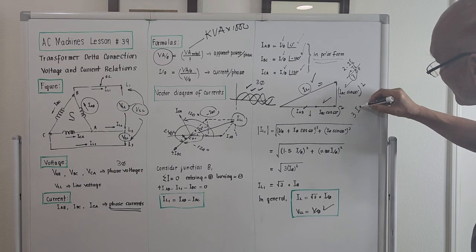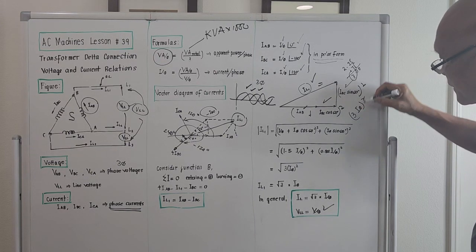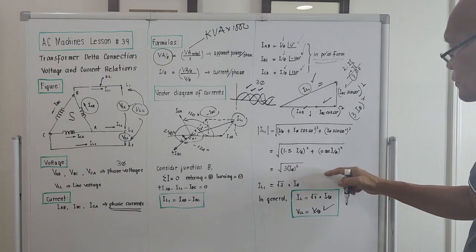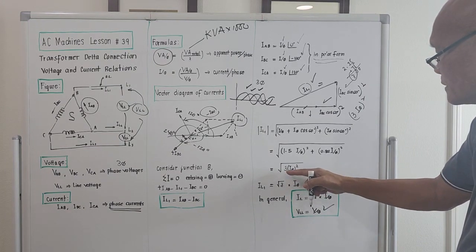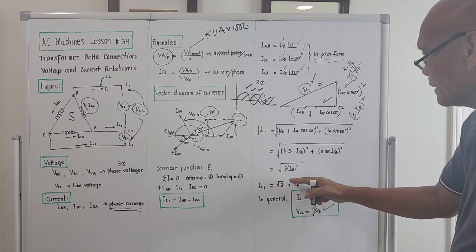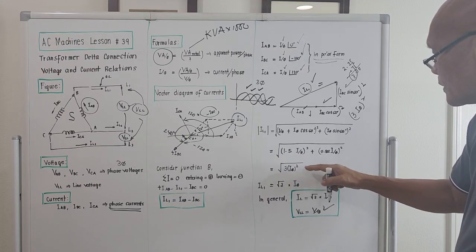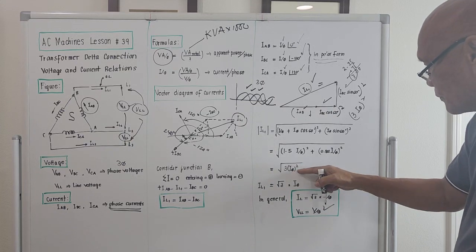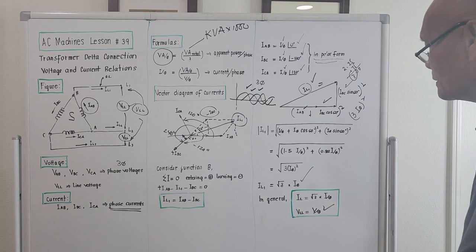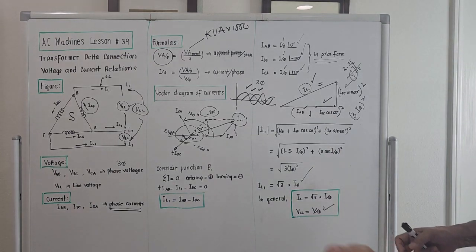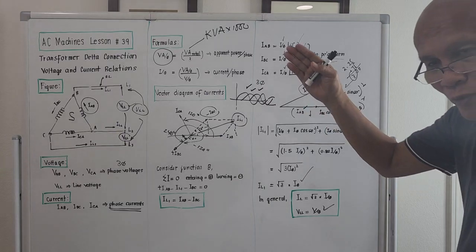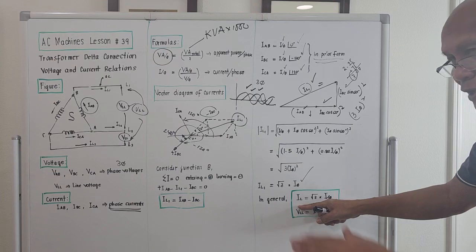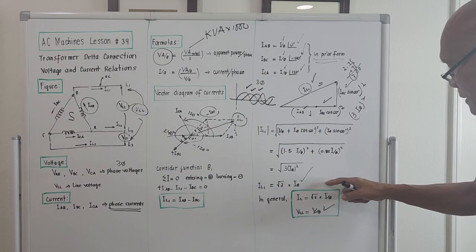But there is a current per phase common factor, quantity squared. 3 is not a perfect square, so we could take the square root separately. The square root of 3 times current per phase squared will be the square root of 3 times the square root of per phase current squared. It's a perfect square, so it will simply be current per phase. So in general, we derive it: the line current for a delta connection will be the square root of 3 times the current per phase.